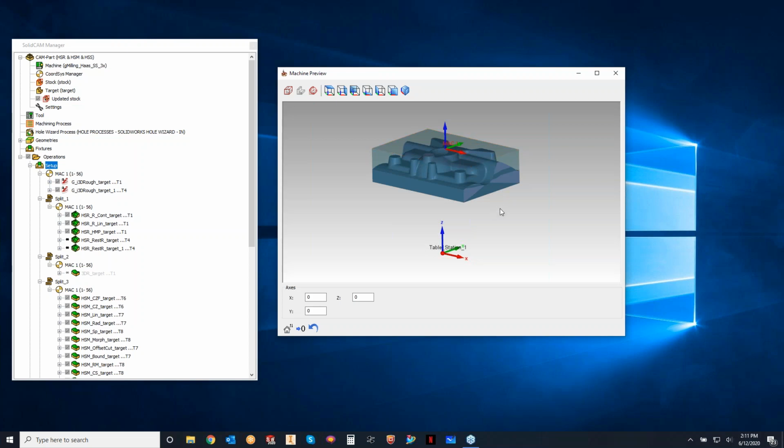No, it's a really good option. As soon as we introduced it, I didn't hear anybody say that no one's going to use this, because it's definitely something that would be highly useful to pretty much every shop I've been in. It's not because someone says, what is Mark thinking, but because it's usually that helpful. Say the material is a little harder or a little softer than you imagine. Even though we plug in things like ultimate tensile strength for our iMachining, sometimes you have to regulate that machining level or change your material definition to that machinability factor that we once talked about. So that sort of thing would come into play as well.